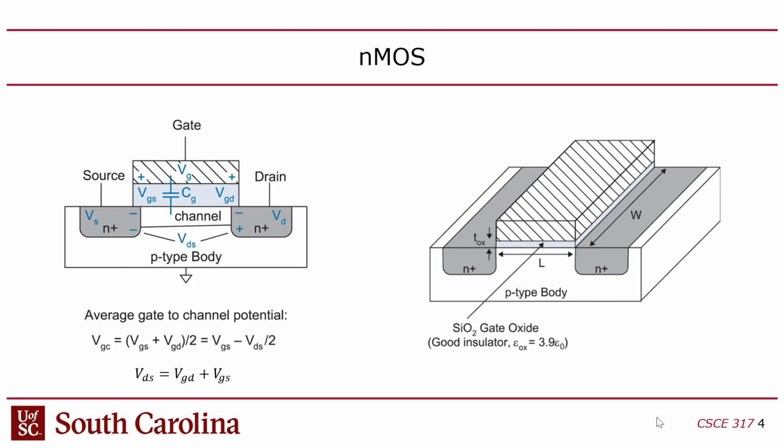Okay, so sometimes you want to drive a bigger load. For example, when we talked about I2C and SPI, you had transistors ultimately that were driving those wires to go off chip. When you go off chip, there's a lot of load there because you have a lot of wire, a lot of capacitance. There's a lot of metal you have to charge and discharge when you're going off chip to long wires.